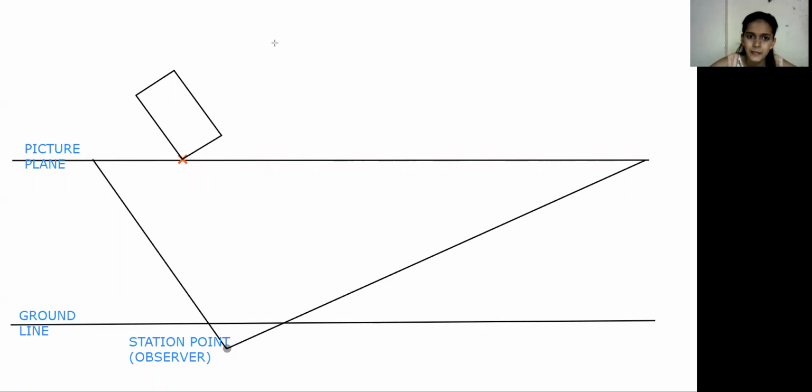Okay, here is the plan. And I'm going to draw the 2 lines between this rectangle. So the plan for 3 steps is completed over here. And you need to show the dimensions in the plan. On this side, the width, as per the scale, you draw it only for 5 centimeter, but you have to write it in meters.